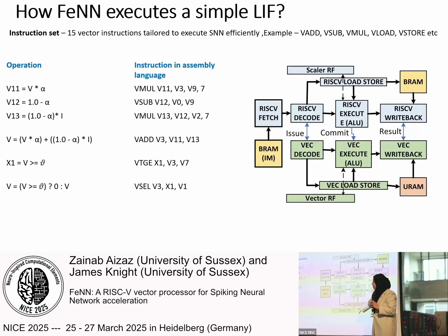Stored in the register file, right? So how does VMAL execute? The instruction is offloaded to the instruction memory by a processor. I will explain in the next slide how it is offloaded. But now the instruction goes, then the instruction is decoded, whether it's VMAL or VAdd, and which registers it wants, okay?